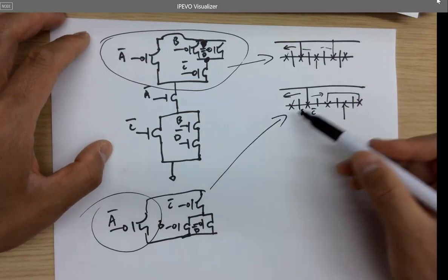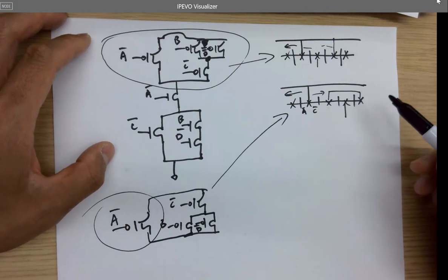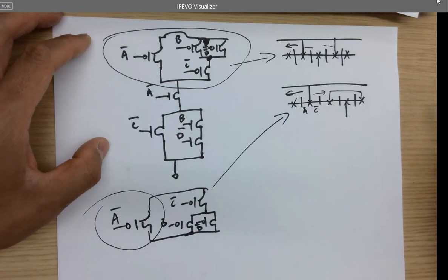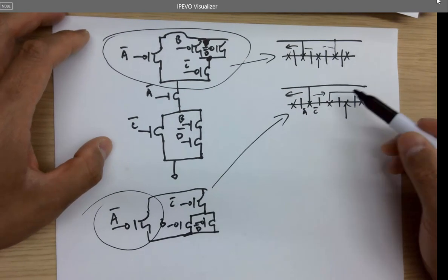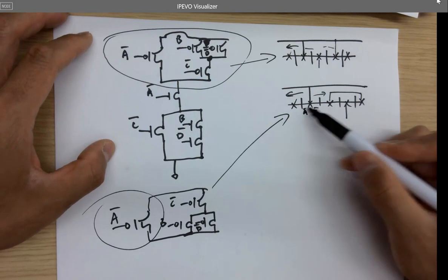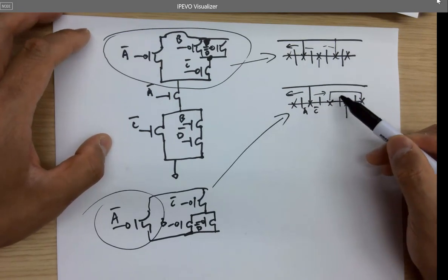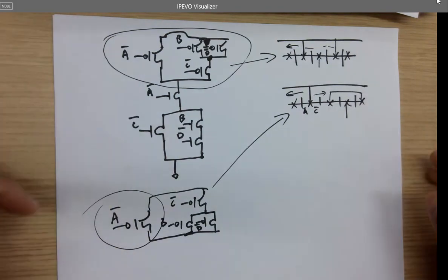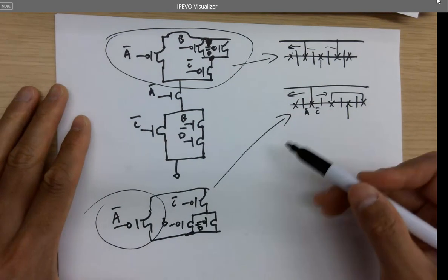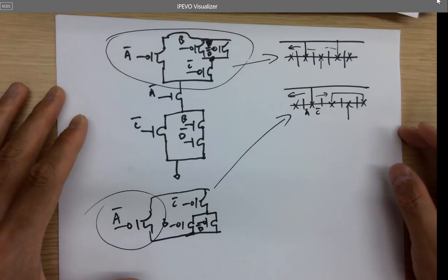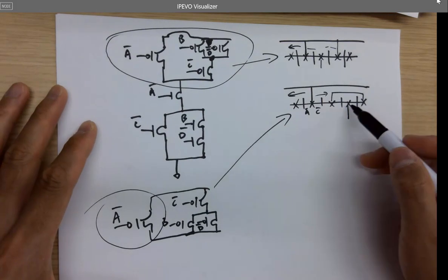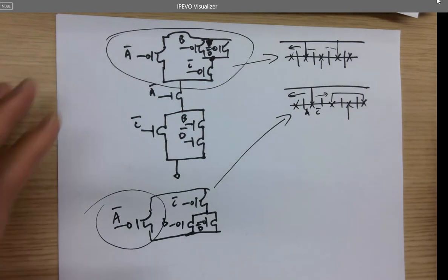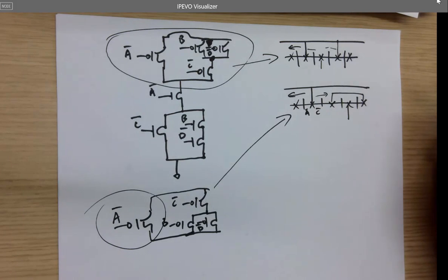It saves a lot of space. So this is a process you probably have to go through when you design your circuit, manually laying out those transistors. It's just optimizing the layout. None of the tools like Cadence or other tools can modify the layout this way, so it only happens when you manually lay it out. You can really optimize the space by designing it like this. The VLSI EDA tools are not able to optimize the layout for you in that way.